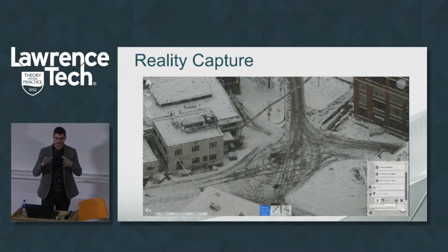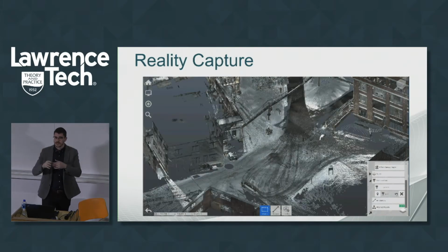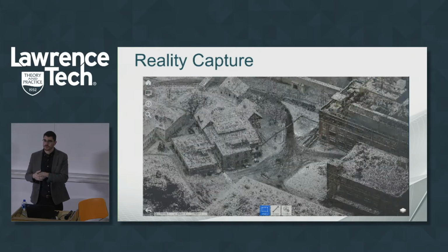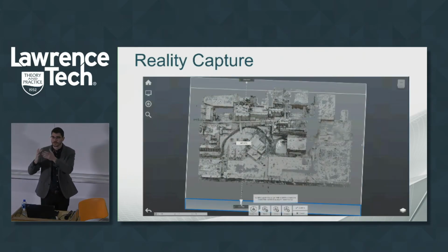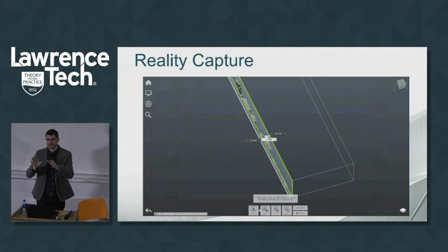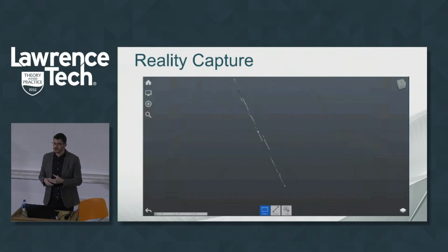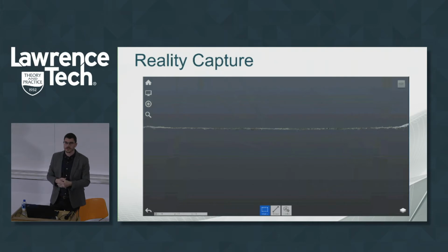Photogrammetry is the stitching of photos together to recreate a three-dimensional object or a three-dimensional space. With laser scanning, you can glean a measurement from a single laser shot. It'll shoot out and bounce back and give you an actual dimension. With photogrammetry, you need multiple photos to glean any three-dimensional data from it. It can tell by the deviation in the pixels from different photos and how much the photo has moved that maybe this building height is 30 feet or so, something along those lines.